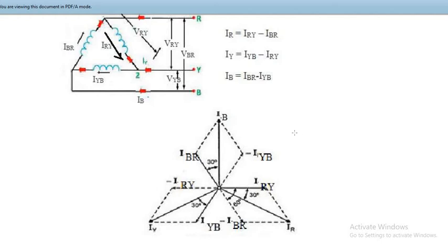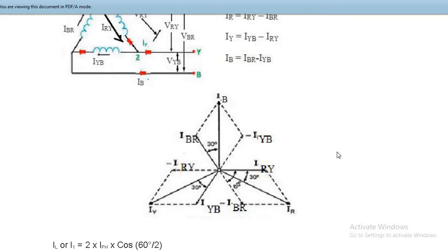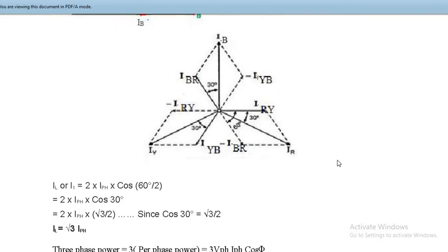Okay, so remember it this way, that when we talk about star connected systems, it is current which is same and the phase voltages are drawn 120 degrees apart. Over here the voltages are same. You can see whatever is tapped across line terminals is same as the phase value. So phase voltages are equal to line voltages, but there is a difference in the phase current and line current. Okay, so what we do is phase currents are 120 degrees apart, and then we satisfy the 3 KCLs applied at these 3 nodes. Okay, don't mug up the things, you just understand it better and you will be able to reproduce it as it is.